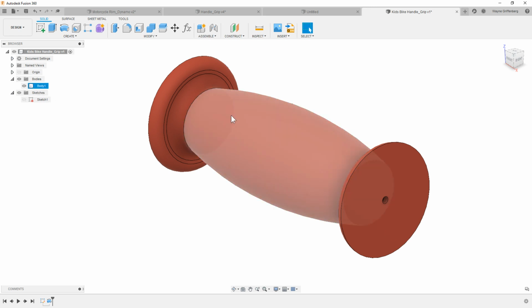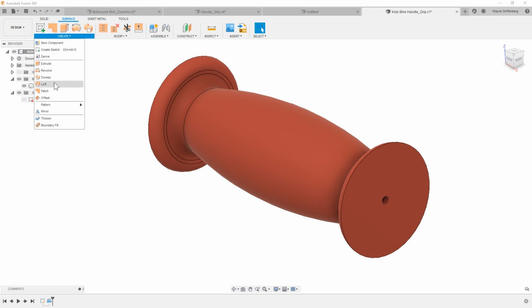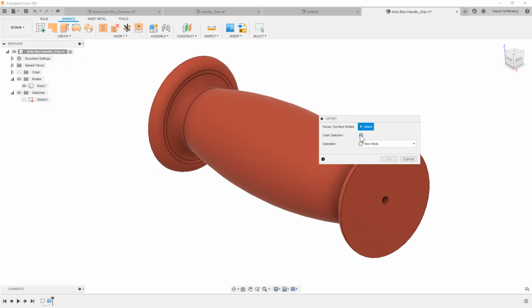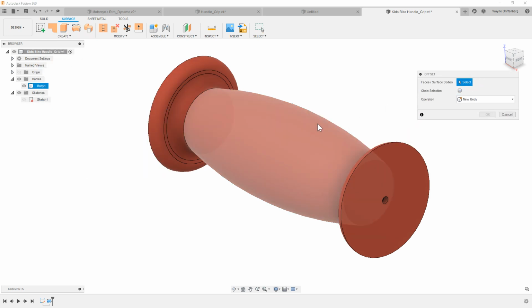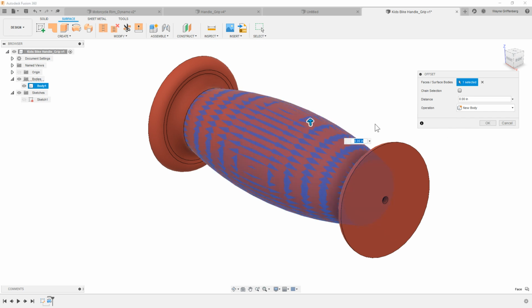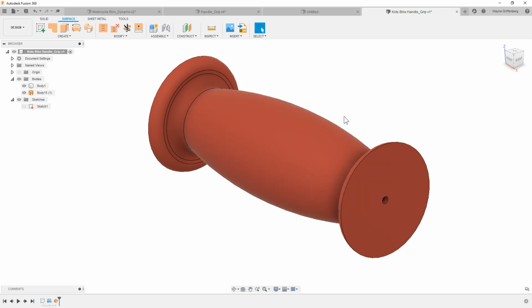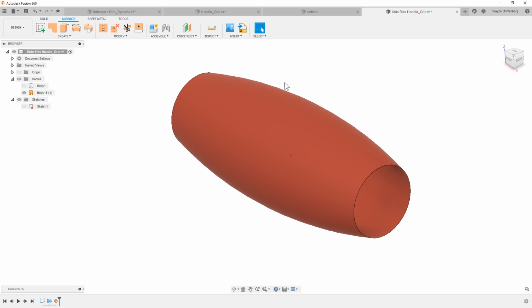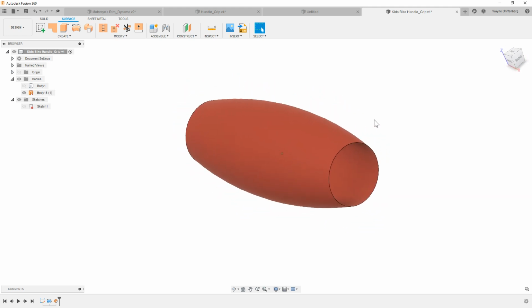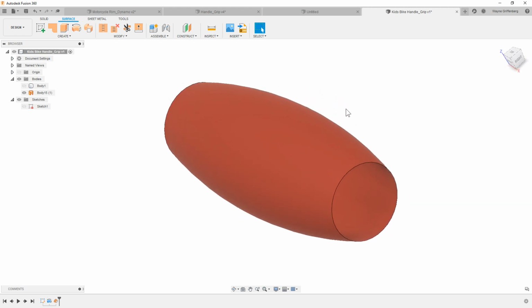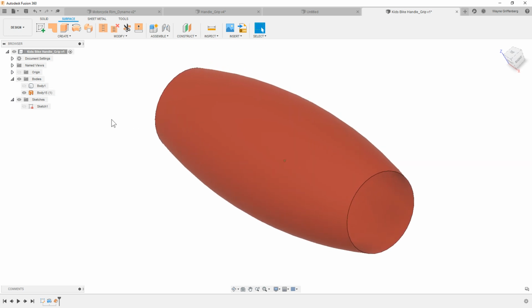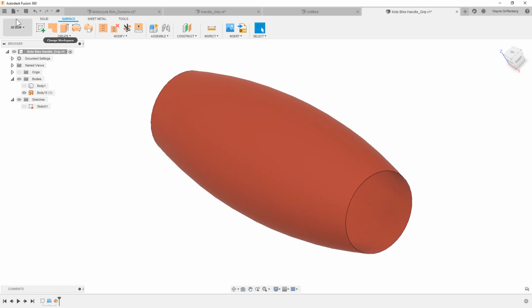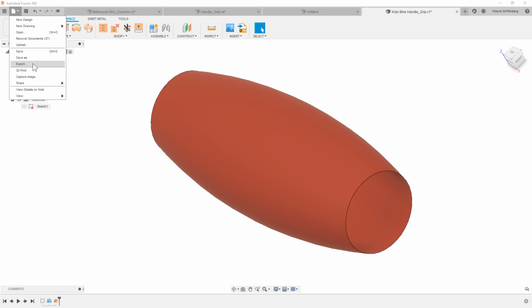I want to keep it simple, so I'm just going to create a surface offset from that face, right? So I want to make sure I'm not going to chain it, so I just grab that one face. So it just created an offset surface. I'm leaving it at 0, so I have an exact surface the same as the model, right? So that surface, I'm going to export as a SAT file that I can work with inside of Dynamo. So I can do that. I can go up here and do a quick export if we wanted to, and I can export that out.